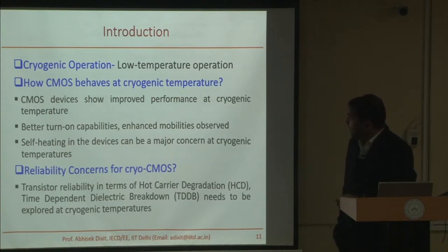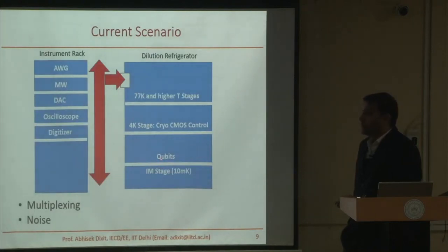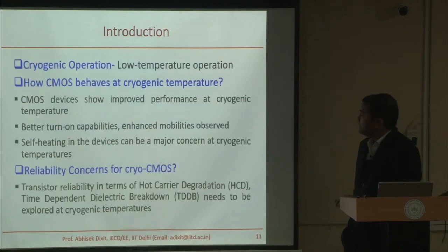So we need to look at those, and then of course some of the old research topics like self-heating is very important as your devices become small. And now remember, you have only 50 microwatts of heating load capacity, thermal load capacity. So if self-heating starts to happen, you may never be able to actually reach this kind of temperature, right? So self-heating becomes very important again.